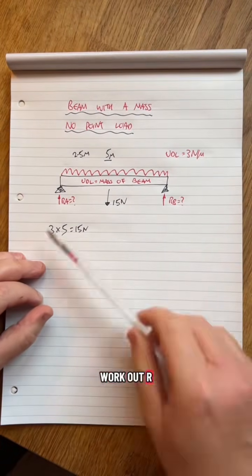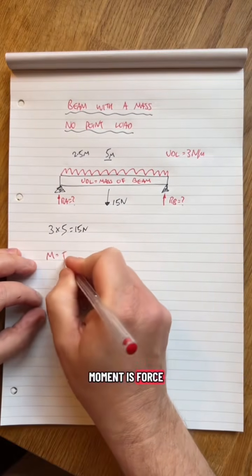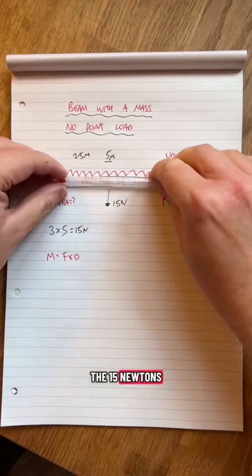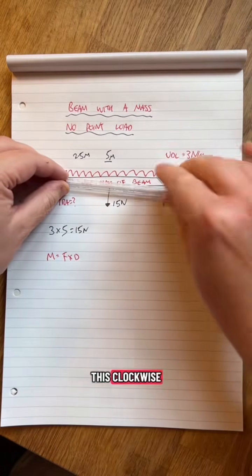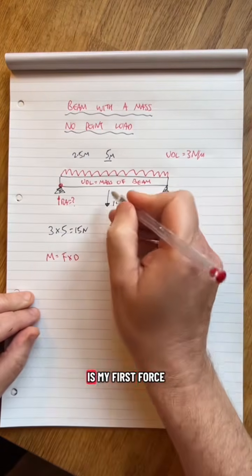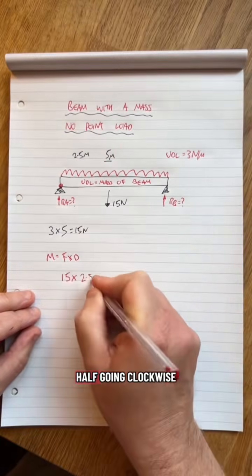Now we're going to work out RA and RB. I'm going to do force times distance. Moment is force times distance. Pivot point is there. The 15 newtons, the UDL, wants to go clockwise. RB wants to go the other way. That's the reaction. Force times distance is my first force: 15 equivalent times, how far is that from here? 2.5. Going clockwise, leave it like that.